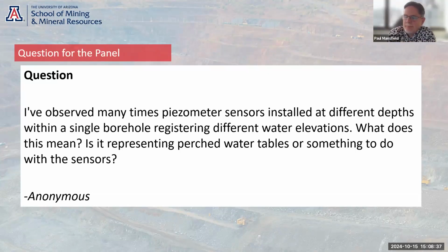One of the reasons that vibrating wire piezometers became the norm in terms of pore pressure monitoring, especially here in Chile in the early 2000s, was because in some of the northern open pits in Chile, in very low permeability environments, open holes or standpipe piezometers were just not able to record representative phreatic levels in a reasonable period of time, because they were so slow in recovering the levels after the drilling.